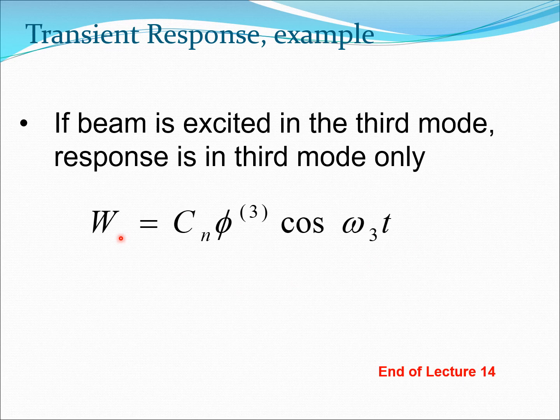Now, one of the reasons many people prefer modal coordinates is they can physically see the behavior of the system. They like to see the fact that if they excite the third mode, then the result comes out in the third mode and so on. So some of these physical manifestations of the reality are very useful for the engineers, and therefore many engineers have a good feel about the response of any structural dynamic system in terms of the modal content, and that's something to keep in mind.